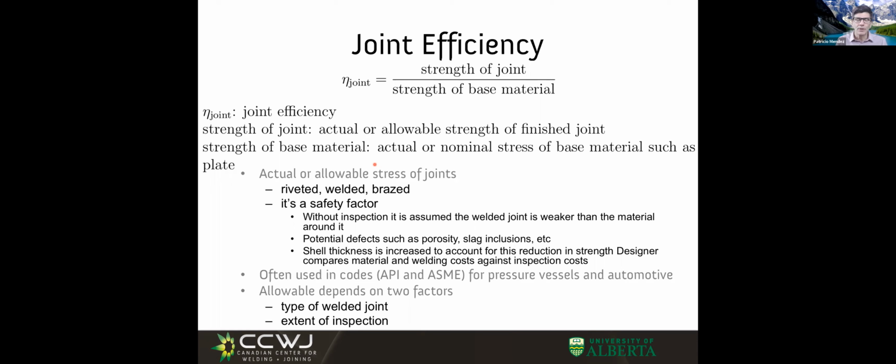The reason I want to bring it to you is because I was once talking with a colleague, and he asked me, okay, how would you estimate the joint efficiency in a butt joint? And I said, the joint efficiency is always 100%, because if you break at the weld, it's a rejection. Only later on I realized, yeah, that's true for us in Alberta.